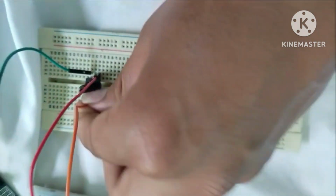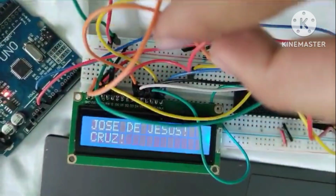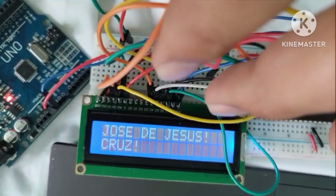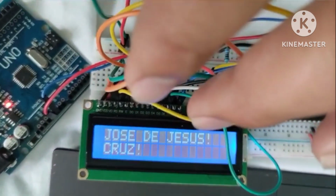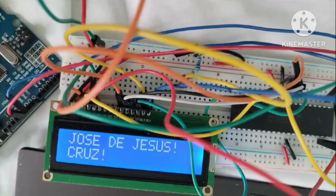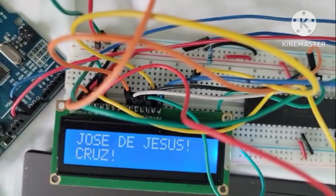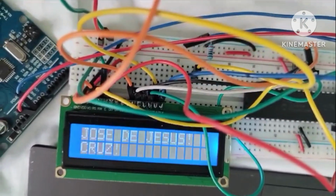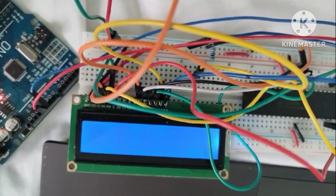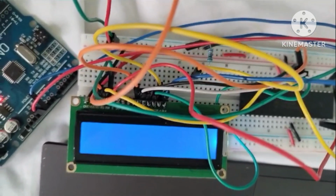This is connected here, and here we can see the two lines. If we increment it, we can see the letters in good form. And if we put the potentiometer at a little bit less intensity, we couldn't see them.